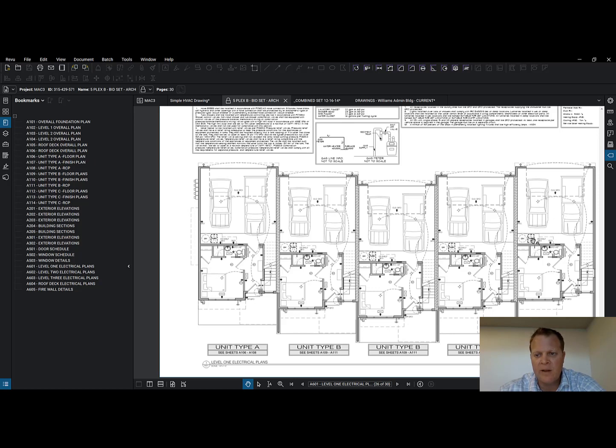So it has to be elevated off the floor. And what is that? The ignition source has to be 18 inches above the floor. So maybe it can't, but I normally see them elevated a little bit more. Maybe my notes are off on that.